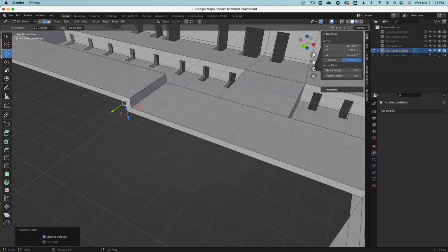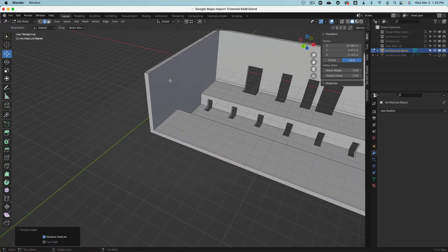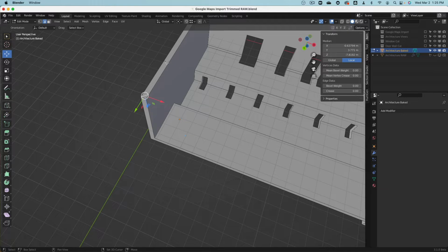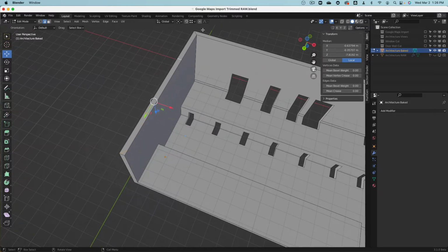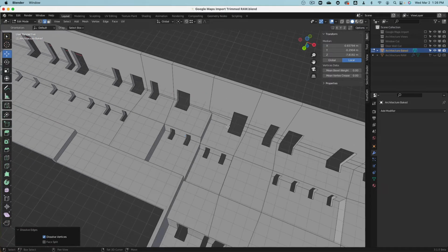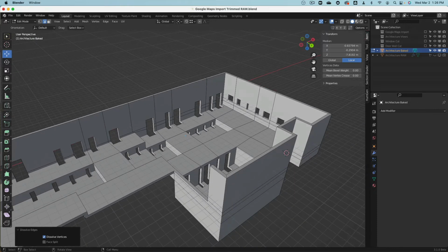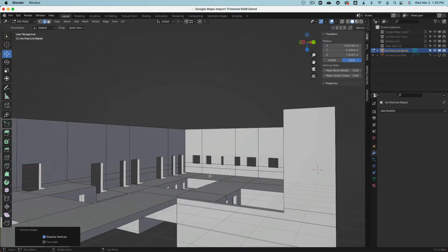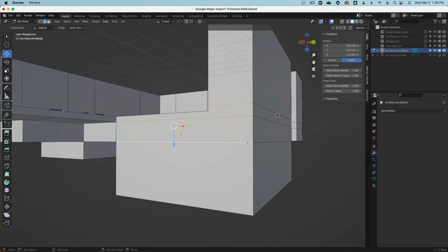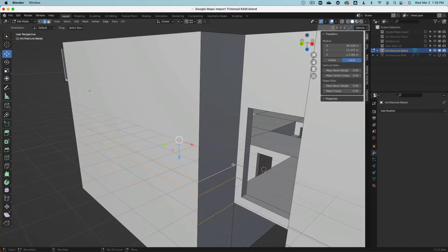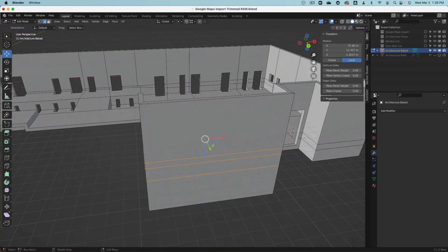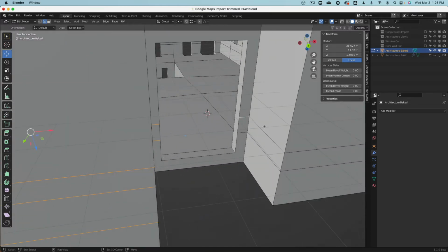What about here? Oh, wow, this is really terrible. Oh, this was the miter line. X and dissolve. For example, here we could select, and dissolve. You have to be careful also that you don't dissolve too much, and then maybe it might remove your geometry in unforeseen ways.